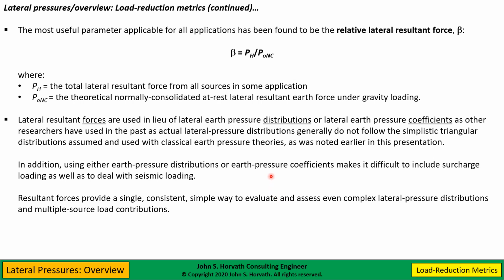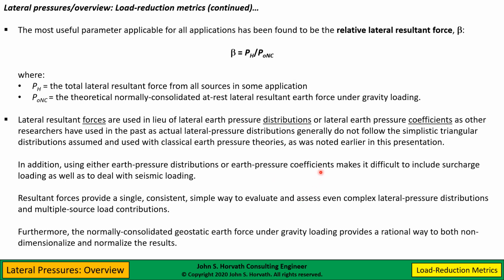So resultant forces are a single, consistent, simple way to evaluate even very complex lateral pressure distributions where you might have contributions from multiple load sources. And as I said, using the baseline, what's the force under a normally consolidated at-rest condition, that's always very simple to calculate in a given application, and it provides a useful way to non-dimensionalize and normalize this factor, beta.